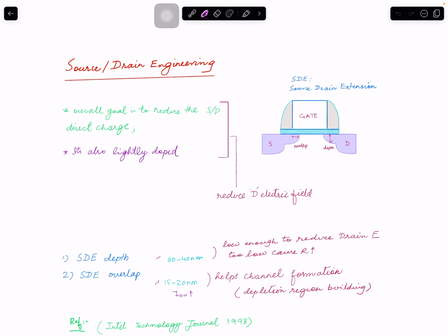So let me draw this. So we have this much area, this much power into the channel here. Now one way is if you reduce the area that is facing the channel. The channel is supposed to be with reduced thickness, we can reduce the channel depth, and it will be here. So the area we actually face might be even less than that, but this is just a picture I drew. The charge that we are showing to the channel here is actually reduced.